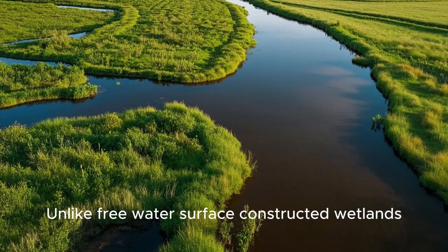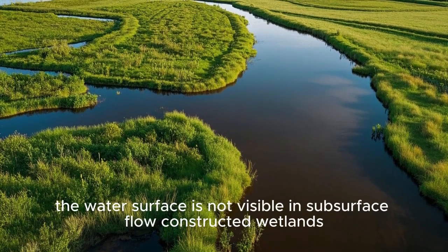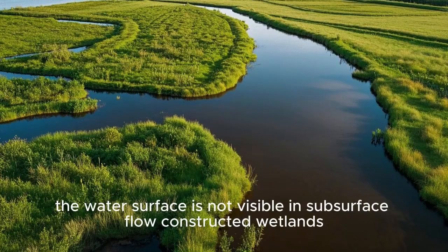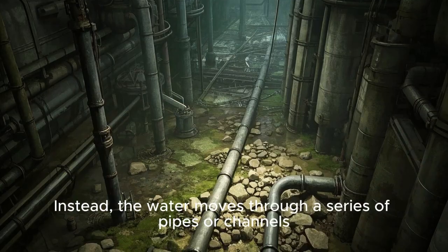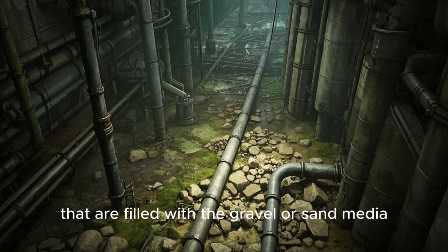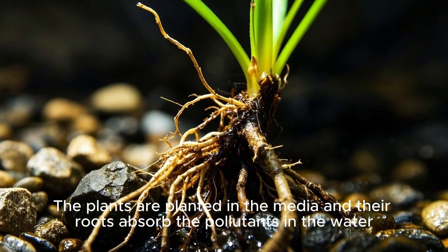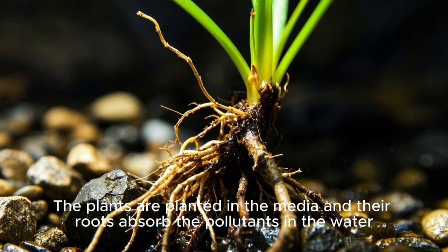Unlike free water surface constructed wetlands, the water surface is not visible in subsurface flow constructed wetlands. Instead, the water moves through a series of pipes or channels that are filled with gravel or sand media. The plants are planted in the media and their roots absorb the pollutants in the water.